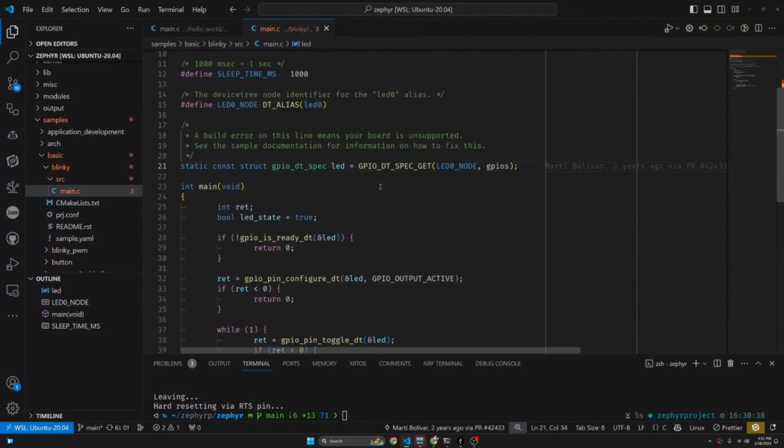And this particular pin, I'm not hard coding GPIO pin numbers like I would in Arduino, like D13 off the top of my head, right? Which is usually digital pin 13 for Arduino. No, I'm asking the Zephyr system for a reference to LED 0, which, depending on the device I'm targeting, might not exist. It could be the case that the device doesn't have an LED, but if it does, I'm certain that I'm going to be able to toggle it and manipulate it as a GPIO.